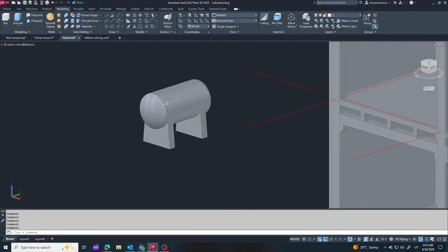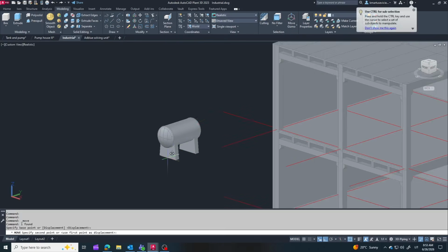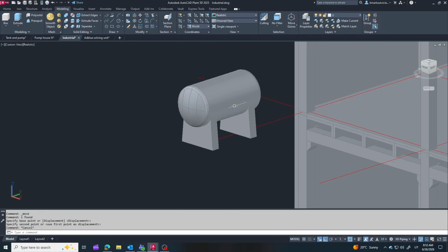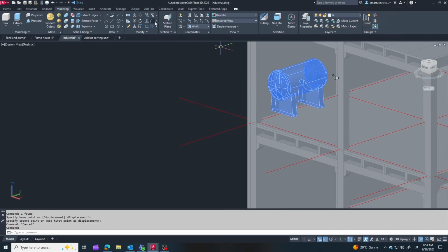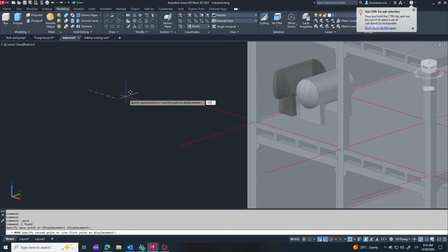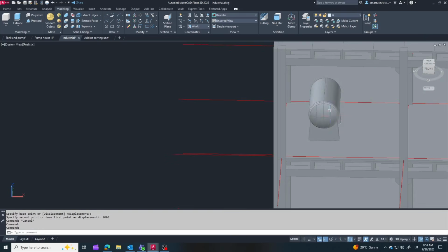I'm placing this tank using the same principles as before. Always leave enough space for maintenance, whenever possible. Since this side is next to a wall, I'm leaving a smaller clearance there and keeping more working space where maintenance access is actually needed.